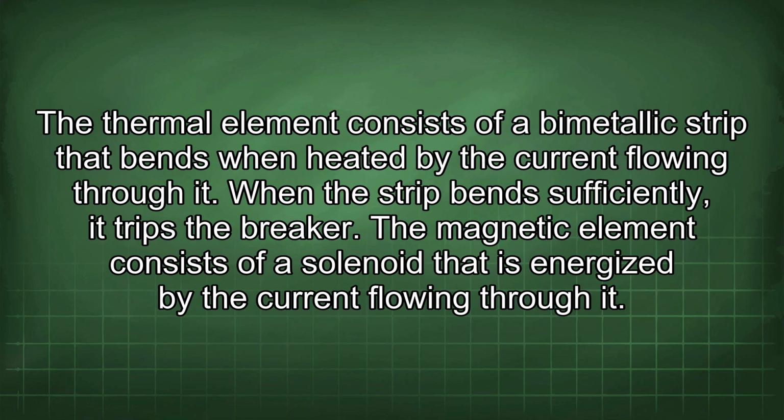The thermal element consists of a bimetallic strip that bends when heated by the current flowing through it. When the strip bends sufficiently, it trips the breaker. The magnetic element consists of a solenoid that is energized by the current flowing through it.